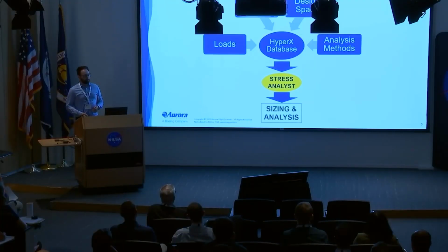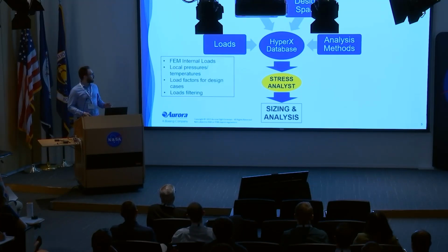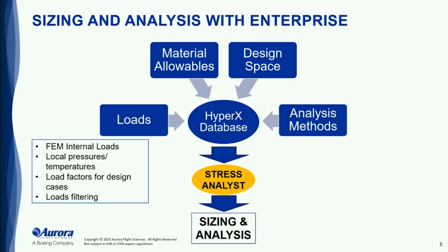Within the HyperX enterprise, you can utilize the HyperX database to help manage a lot of these sets and keep a consistent flow as you're starting from the top down and spreading out to your contributors. So for Liberty Lifter, for example, we're able to generate FEA loads that are controlled within the database and apply any local pressures, temperatures, and factors that are relevant to specific areas, as well as what filtering criteria we want to apply on different sets of the program.